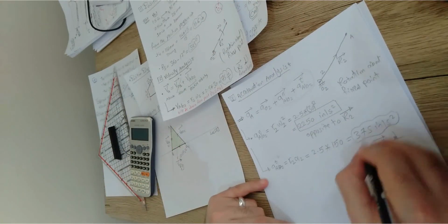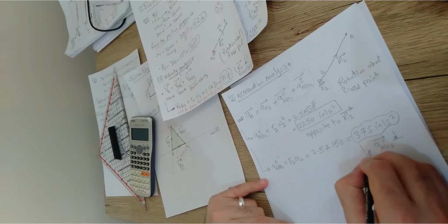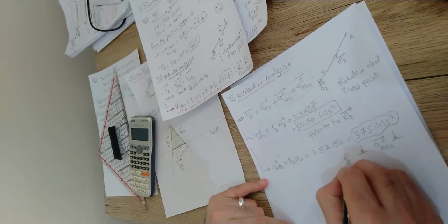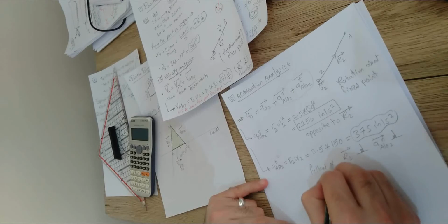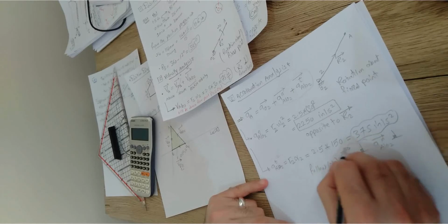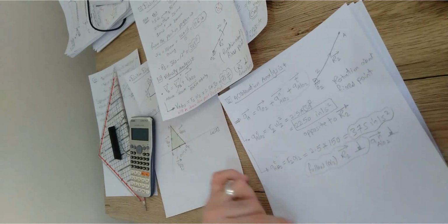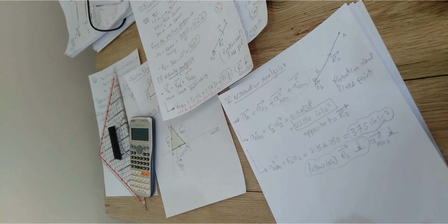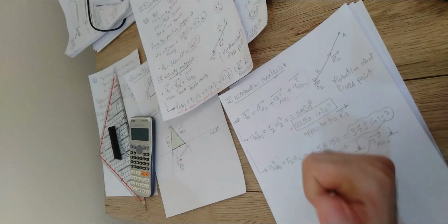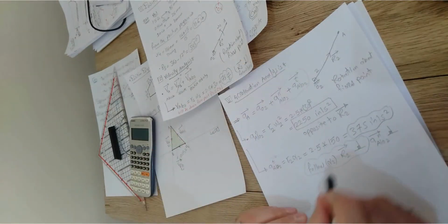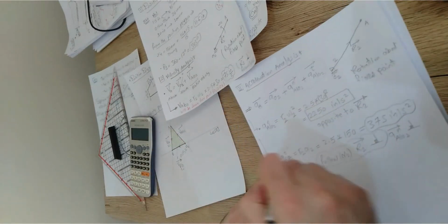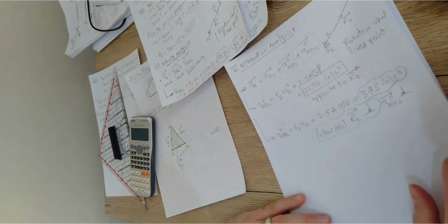It means that I can also say that the tangential component is perpendicular to the R2 vector and follows the direction of omega 2. Follow the direction of alpha 2. It is very similar to the relative velocity of the same length. The relative velocity should be perpendicular to R, and in addition, it should follow the omega of this length. Here it should be perpendicular to R and follow the alpha, the angular acceleration of the same length.